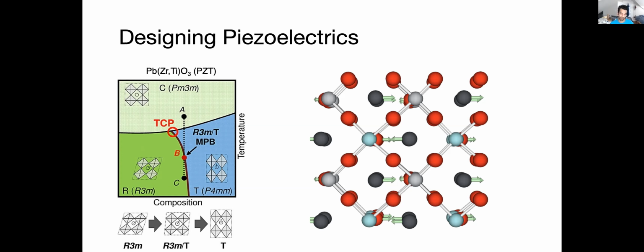And if I'm talking about a 50-50 alloy, I could be talking about hundreds or millions of positions in order to compute anything. And if you've ever played with density functional theory, which is the tool we like to use in the Materials Project, you're not really going to scale beyond, say, 100 to 200 atoms. So it's a challenge in the sense that it's very difficult to compute something on that large a scale. The combinatorics are a challenge, but we don't really have good tools to scale there.